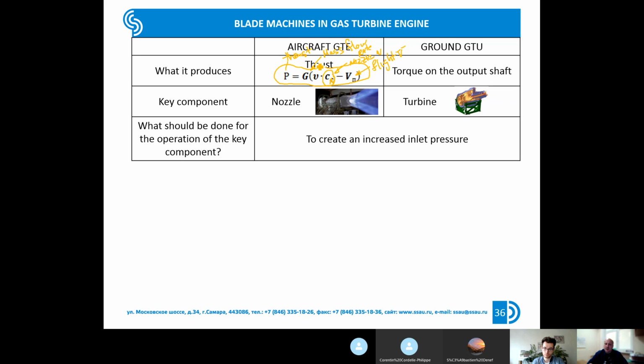That's why you need to take into account the changing of the mass when the working fluid comes through the engine. So this is the momentum conservation equation, not mass. In Russian practice, it's the Stechkin equation.